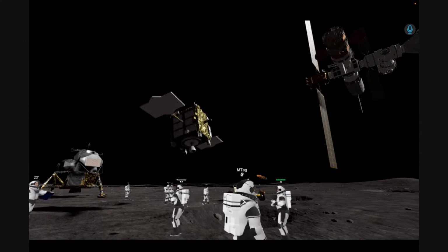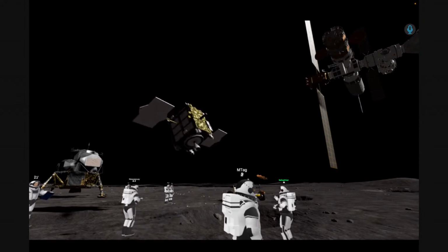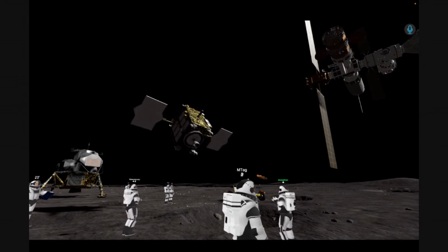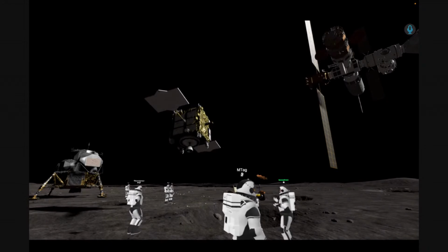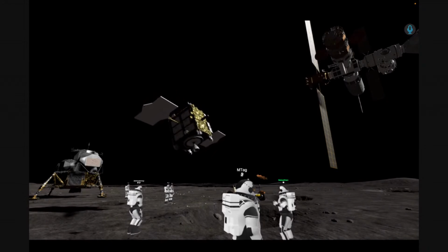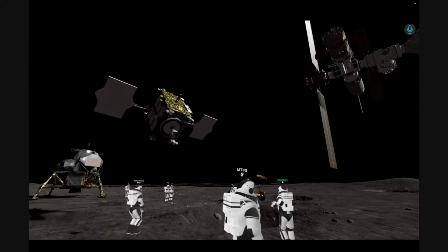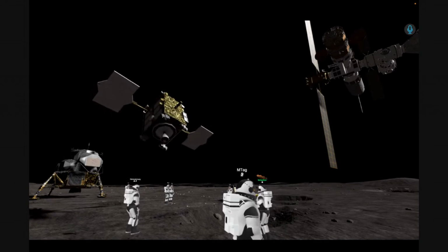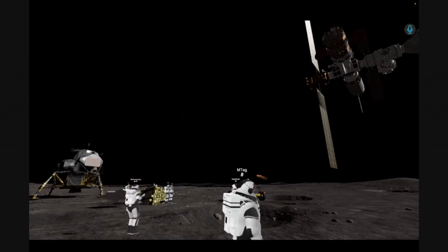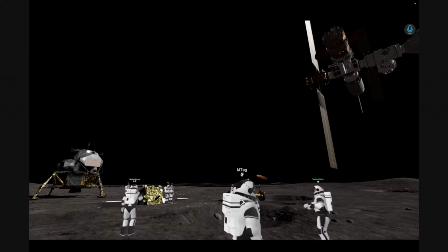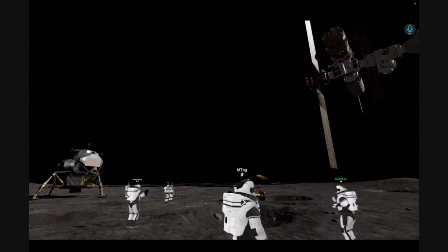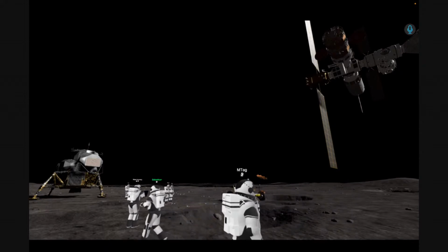But coming back to the mechanical part, you need resistance. You need to be good from the weight point of view. You also need to think about grounding and electrostatics. If your material gets charged so easily, that can be a problem for the electronics, right? Because if the structure is charged and then it's discharged into one of the microchips that control the satellite, the satellite can stop working. So we have to be really careful about all the decisions we take. And sometimes, sadly, this is what happens when you launch a satellite without knowing all the consequences of the design decisions that we're taking.